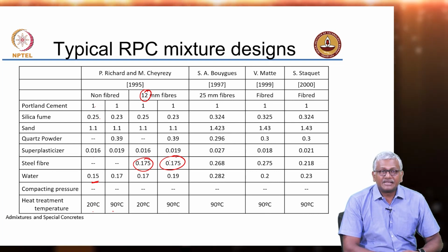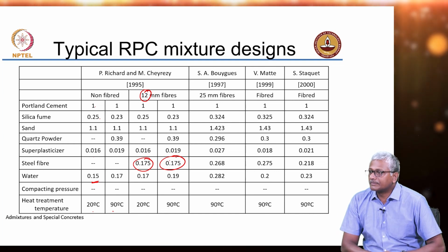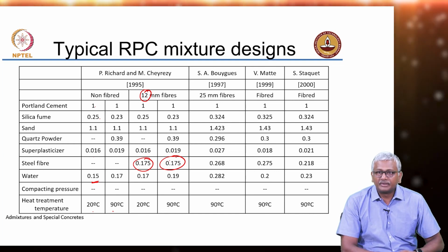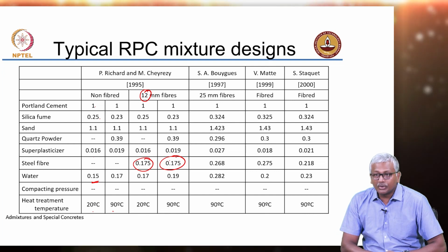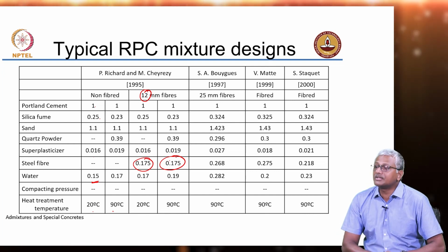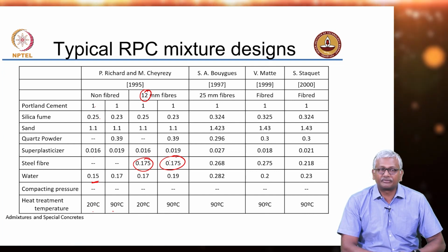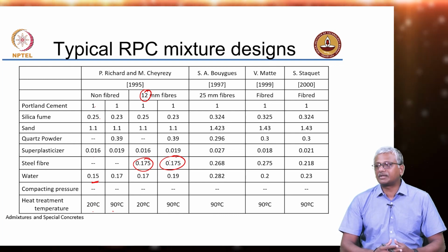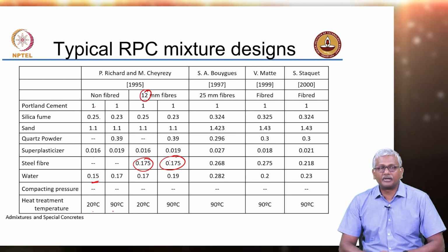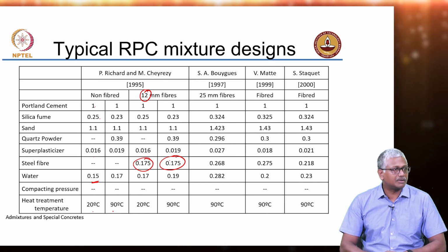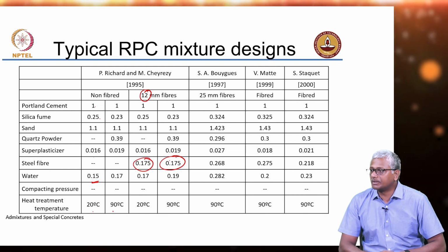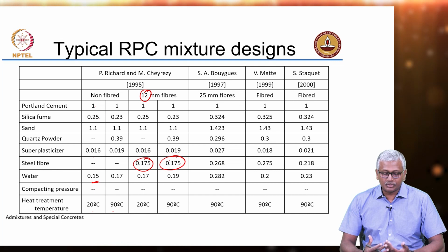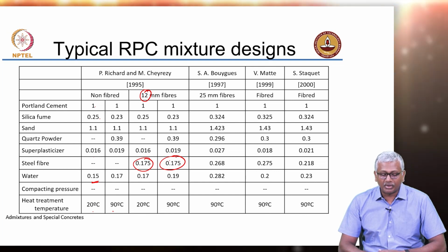The density of steel is about 8,000 kilogram per cubic meter, right. So, you are talking here about a significantly large amount of steel fiber in your system, and that is going to cause tremendous problems with your workability. When you put fibers in your concrete, it's going to create problems with workability. So that's why super plasticizer becomes even more important in such a case.